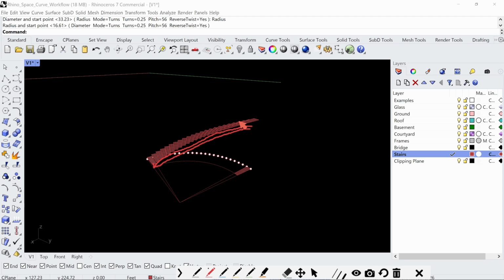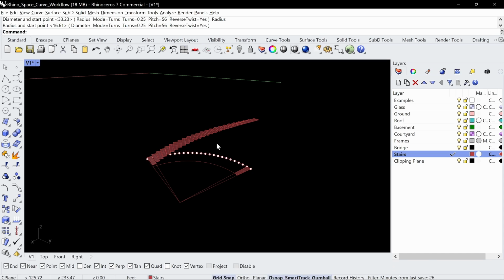And if you're doing an open riser, like what we're doing here, we want to draw the helical structural support underneath of that. So that's why it's really important to do a helix. The same goes for the guardrail, which has to follow that. So we're going to use a command called helix.